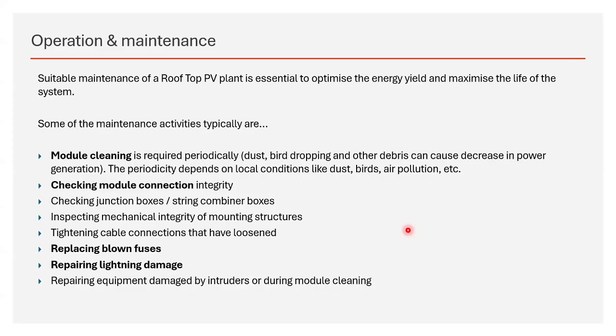There has to be a preventive maintenance schedule, monthly or weekly as recommended by the OEM, and we need to perform these checks. Similarly, for the junction boxes, any kind of heating, hotspot, and the tightness check has to be performed. Structural and mechanical integrity checking in between is also very, very important. Otherwise, with a cyclone or such things, the entire supporting structure may get uprooted, which will cause extensive damage to the solar PV panels.